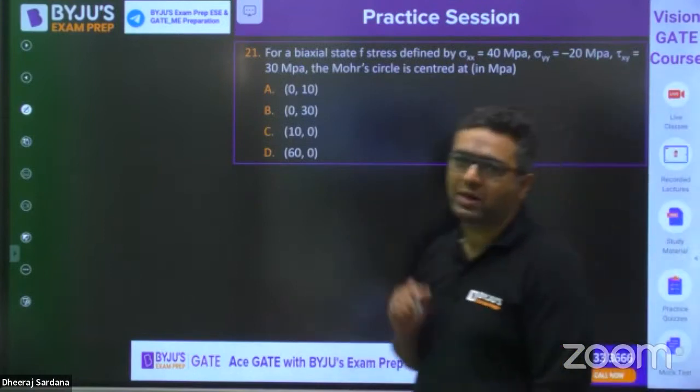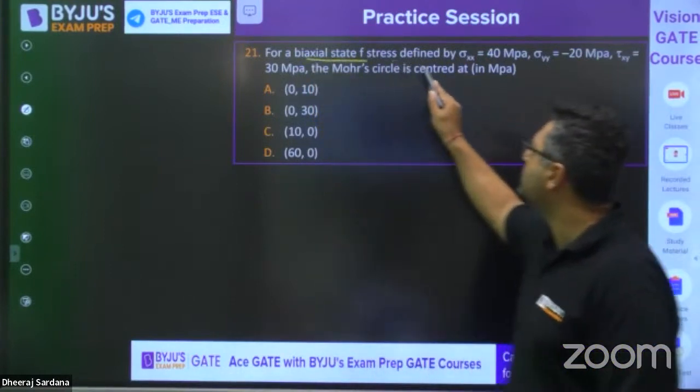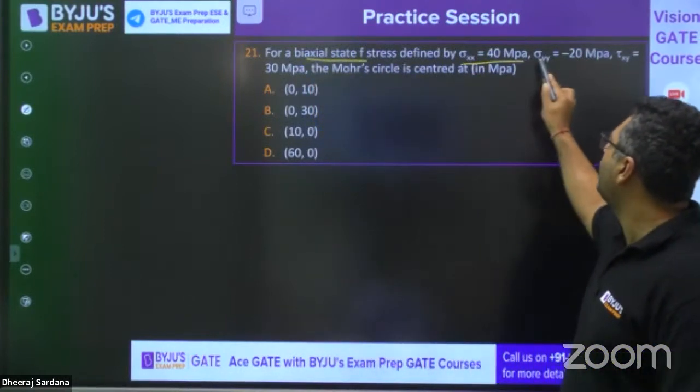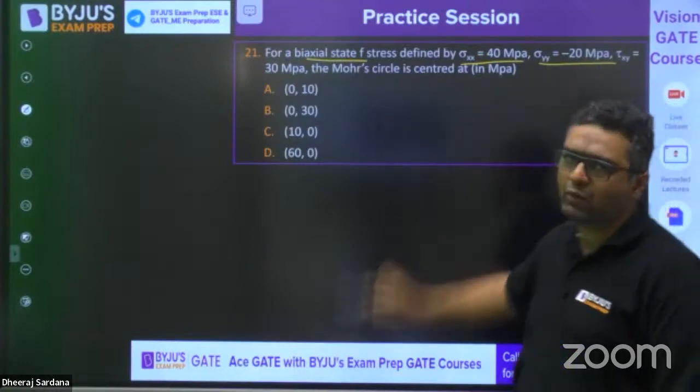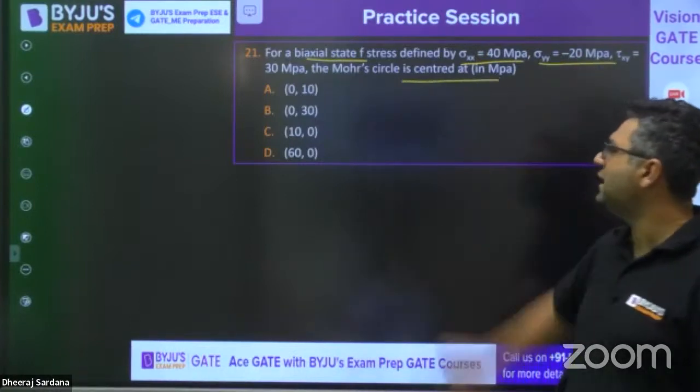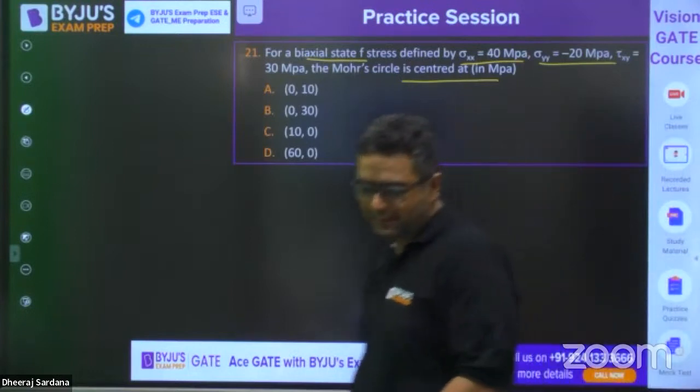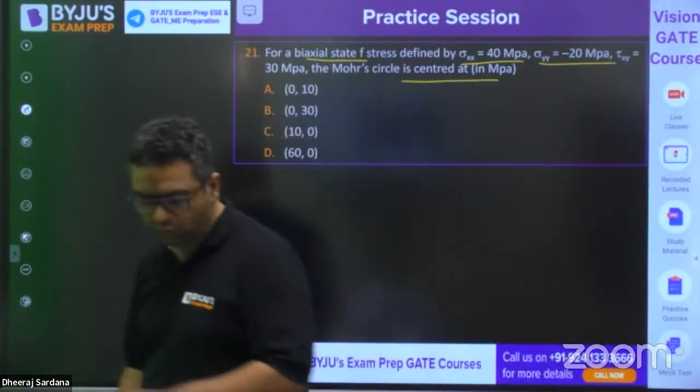Last question from Mohr's circle. For a biaxial state of stress, sigma xx 40, sigma yy minus 20, tau xy 30, what will be the center of Mohr's circle? This time I want answers from all of you.